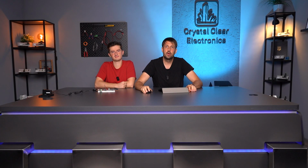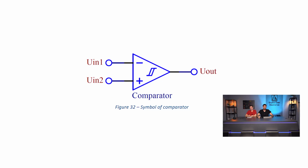Comparators that are available in stores are such operational amplifiers that have beneficial parameters when used as comparators. However, if we use them as operational amplifiers, they have some suboptimal features. It's important to remember that operational amplifiers are mainly used for amplification, and comparators are mainly used to compare voltage signals. In terms of their basic operation, there is no difference between them. In schematics, the comparator and operational amplifier are usually marked with similar symbols. If a comparator is explicitly marked, it is usually as shown in the diagram.